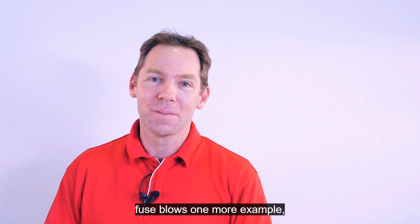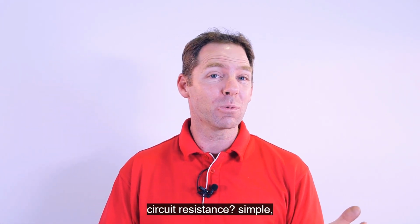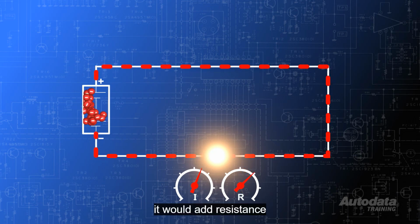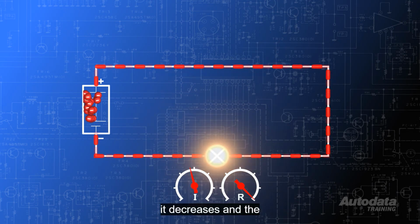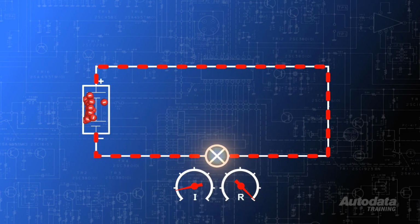One more example. What would happen if there was corrosion in the bulb socket? How would that affect total circuit resistance? Simple. It would add resistance. So what then happens to the circuit current flow? It decreases and the light appears dim, or it doesn't operate at all.